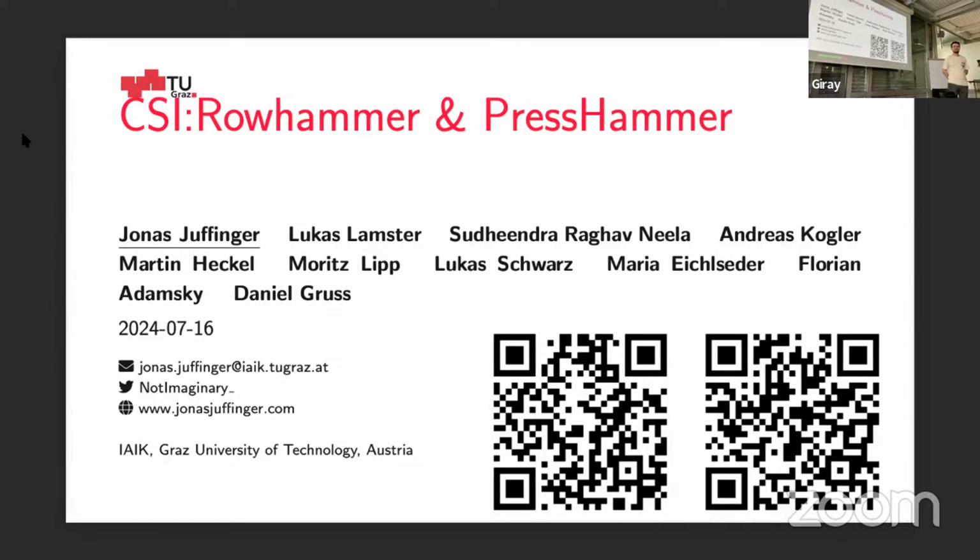Any questions? I can make a comment about undervolting at the end. I did a lot of experiments with reducing voltage for DRAM chips. What we observed in general was, you reduce voltage down to some level which is still within the guard band, and you don't see any bit flips. Let's say you reduce from 1.3 volts, 1.2 volts down to like 1 volt. You don't see any bit flips, and then you see a few bit flips at that point. If you increase your access latencies, it's already enough to avoid those bit flips in most cases.